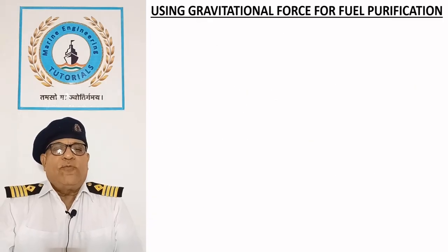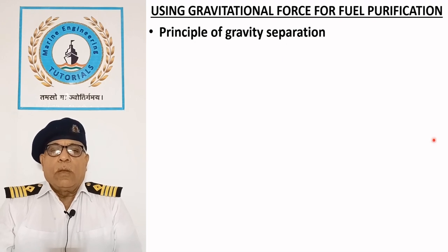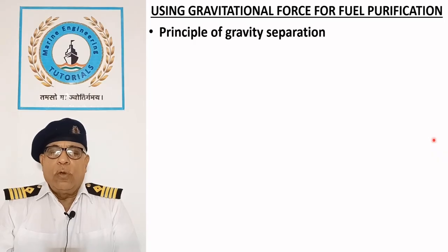Using gravitational force for fuel purification. Principle of gravity separation. Fuel oil before use is allowed to stay in the settling tank, where solid particles and water settle down by gravity due to density difference.